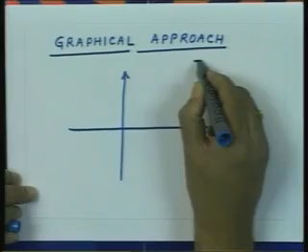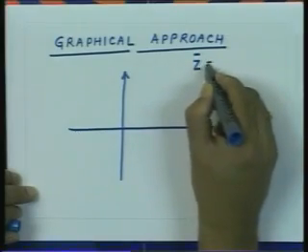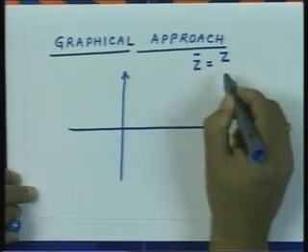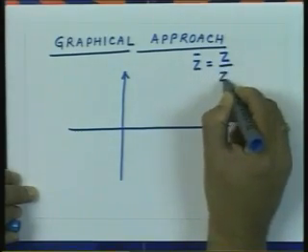In our framework now, let us first make an assumption that the transmission line is a lossless transmission line. That means the characteristic impedance of this line is a real quantity, and all impedances which we have are now normalized with respect to the characteristic impedance Z0. So, any normalized impedance z is nothing but the actual impedance divided by the characteristic impedance Z0.